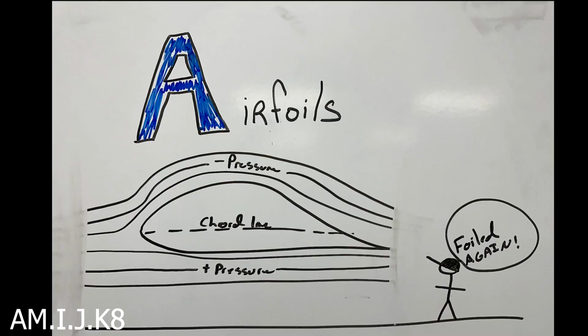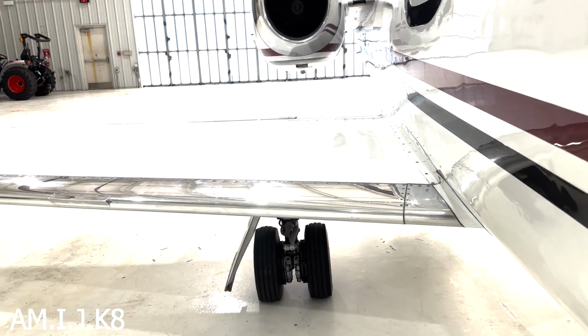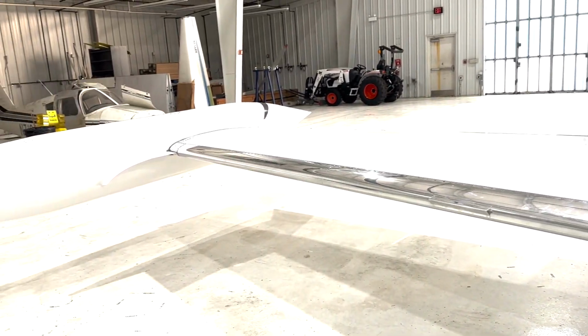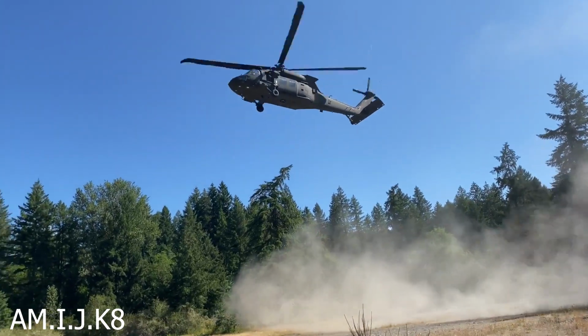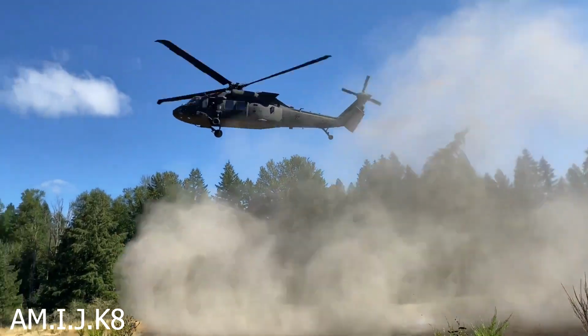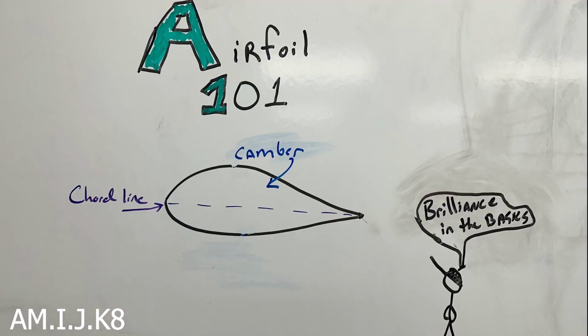Airfoils are fundamental to understanding how aircraft generate lift and propulsion. An airfoil is essentially any device that, by either applying Bernoulli's principles or Newton's laws, generates a force when air flows over its surface. This principle applies to various components of aircraft, such as the wings of airplanes, propeller blades, helicopter rotor blades, or the fan blades of turbofan engines. In the case of helicopters, these rotating blades are often referred to as rotary wings, highlighting their dual role in creating lift and thrust.